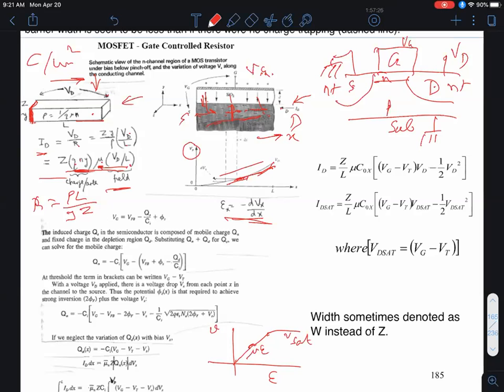Like I said, I'm writing the simple resistor formula in a very funny way so that we can make the correspondence to the MOSFET in a second, okay? So the point is, the current is proportional to the width of the resistor, and it makes sense, right? The wider the device, the more the current, times the charge per unit area, looking at it from the top, times the drift velocity, which is mobility times electric field, if the electric field was low enough. If the electric field was high, mu times this electric field has to be replaced by V_sat. Okay? And that's what we'll have to do in a short channel MOSFET. We'll see later on. Everybody with me?